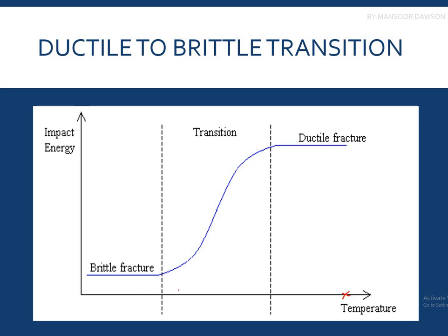But they sent the ships into a very low temperature, around 0 or sub-zero. Immediately, the body of the ships started to crack. So that failed the Liberty ships, and some of the ships which were made in a time of 3 or 4 weeks cracked immediately when they were sent into the ocean.